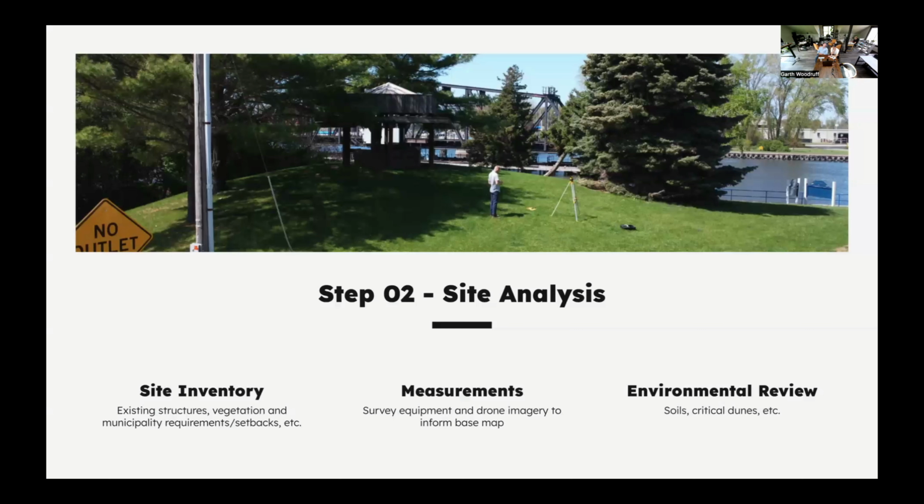And then that gets dumped directly into CAD. Yeah, so that survey tool, you're recording your data on an app, and then that app will export all of your points or lines as a DXF file, and then you can take that file and directly import that into CAD to help create your site surveys and that base map.